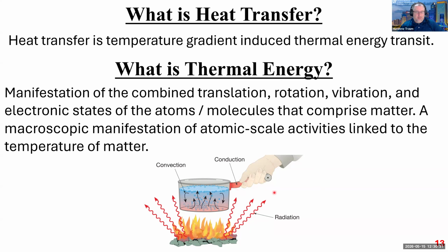I should just mention for completeness, there are other modes of heat transfer other than these three. They are usually very, very small compared to these three modes of heat transfer. A lot of times they only occur in very specialized situations, like when something is really, really small, on the nanometer scale, or if you have a gas that's incredibly rarefied and you're in Knudsen flow, you can get heat transfer that's carried by individual molecules. But for our purposes in this class, most engineering applications only have to worry about conduction, convection, and radiation.